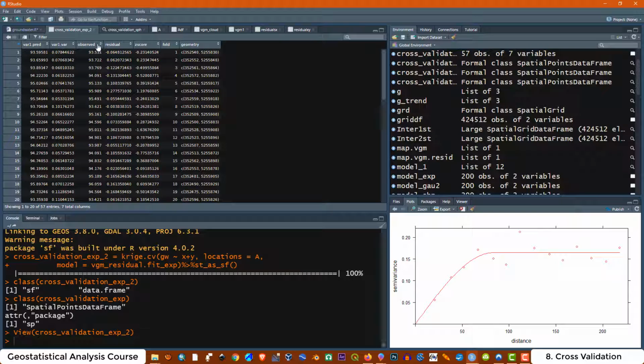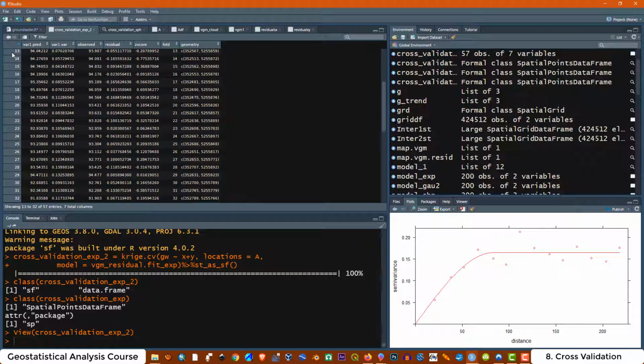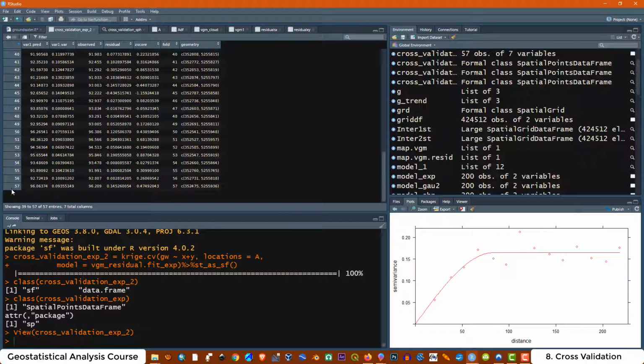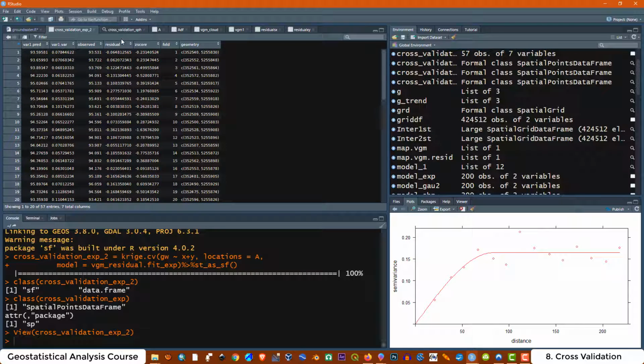That's the data we get at the field when we measure the groundwater table, and we make the calculation to calculate the groundwater elevation. The residual values, in this case, sorry, I'm going to put this one in order. That's for the 57 piezometers, from 1 to 57. The residual value is the difference between the predicted value and the observed value.